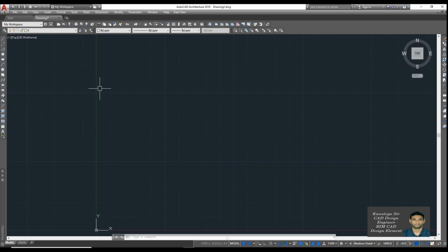To create this workspace, we go into Customize Interface, and here we are going to save it as Current and give it a name. Here we are going to add the name Classic and hit Save. Now this workspace has been saved with the name Classic, and as you can see here we get a workspace called Classic, and then we can use these tools as we did earlier.